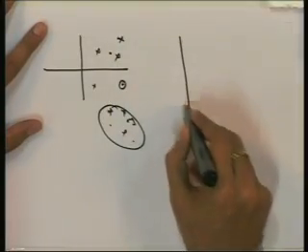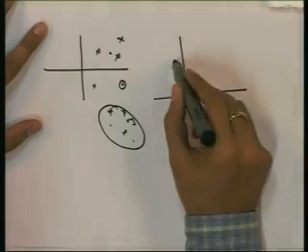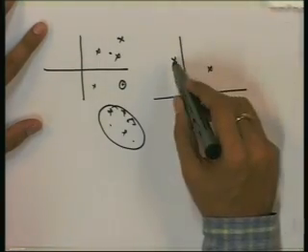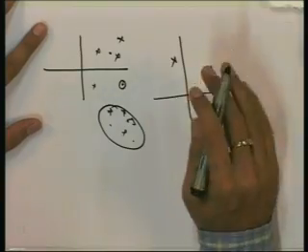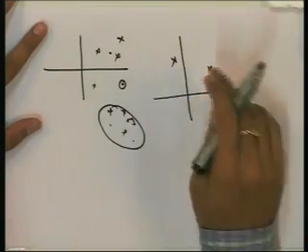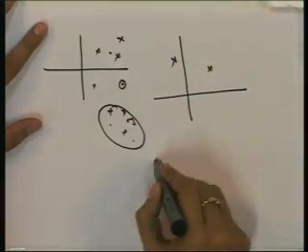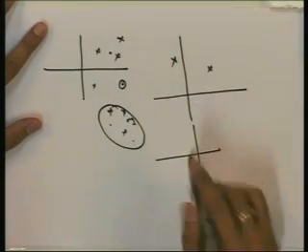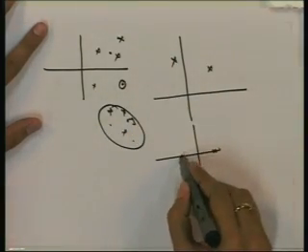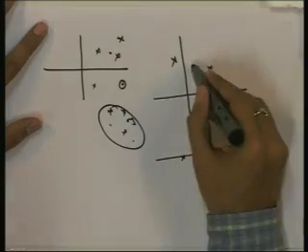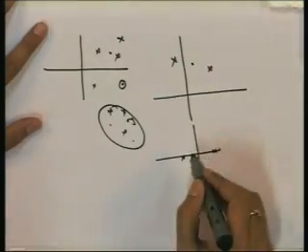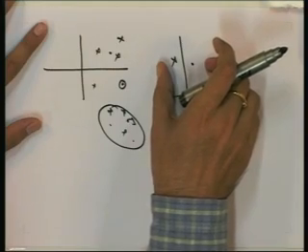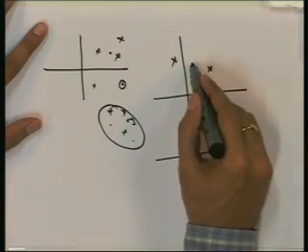Suppose we are given a binary signal set, so 2 points. If it is 1, it transmits this, if it is 0, it transmits this. Now someone uses this signal set. I can say that I will not use this signal set, I will instead translate it and then rotate it appropriately so that the signals are here. So I will rotate the signal set around the midpoint here to make it horizontal, and then shift it to bring this point here.